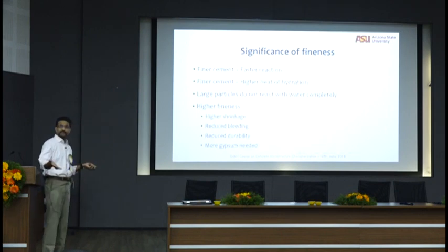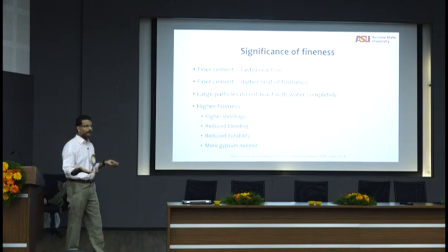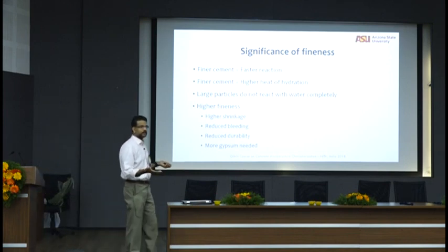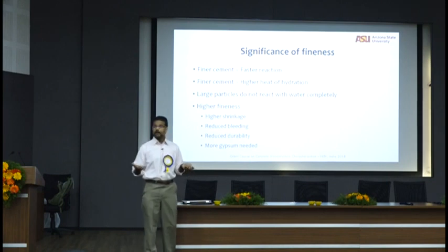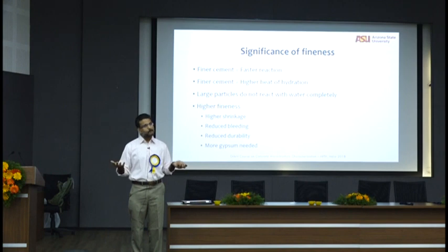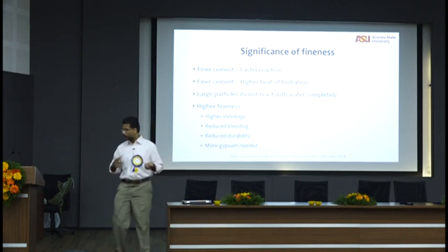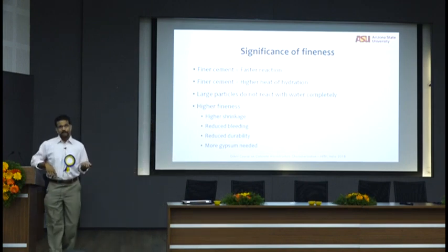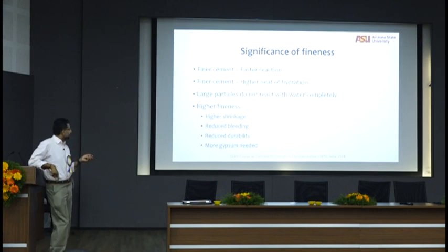Fineness: finer cement, faster reaction. So it has to be good, right? No? What's wrong with faster reaction? More heat of hydration. What's the problem with more heat? Likely to crack if you don't have enough heat transfer to the outside. Large particles do not react with water completely, which is perfectly fine.